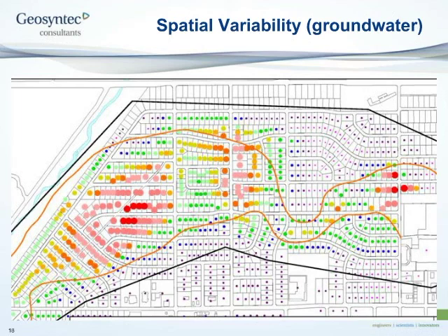But what was not recognized at that time was that there was a bedrock knob in this area, and the groundwater was diverted around that feature through another channel, and an entire plume of VOCs and groundwater existed to much greater distances than were originally considered.